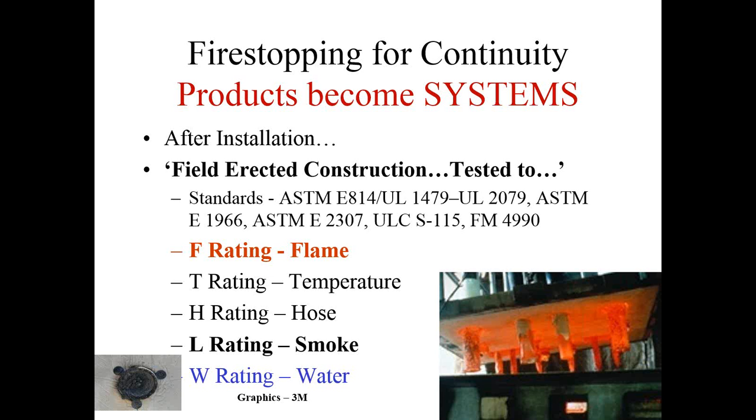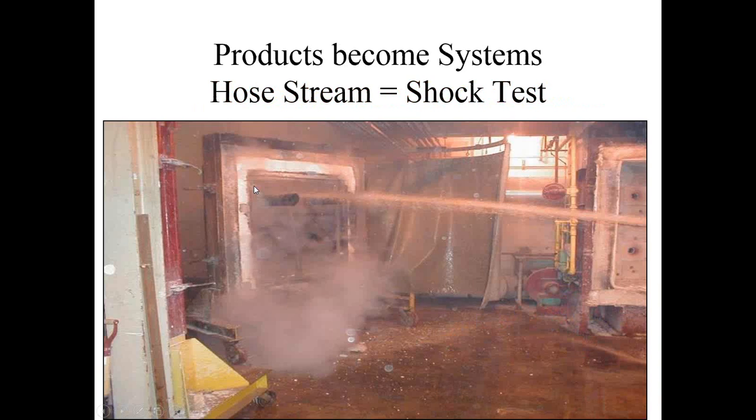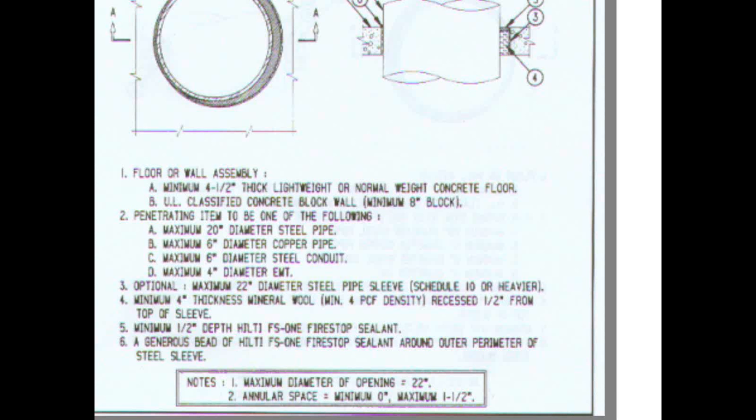There's one other test that doesn't come up often that sometimes the fire resistance rated construction industry uses, and that's UL 1709, which is a high energy fire. It's a petroleum-based fire. It goes from 0 to 2,000 degrees in about 5 minutes, and then stays at 2,000 degrees for the duration of the test. That's kind of the oil and natural gas industry. Maybe some of the firestop manufacturers have done some testing on it. You'll have to check with them on it.